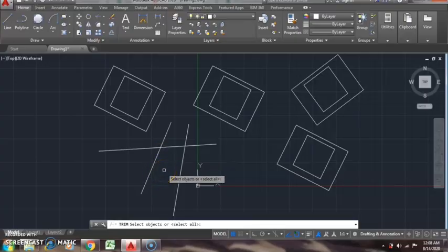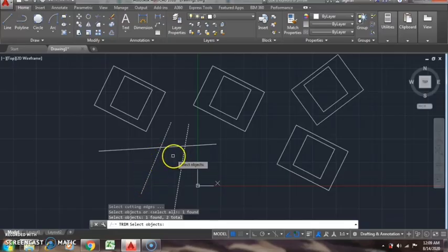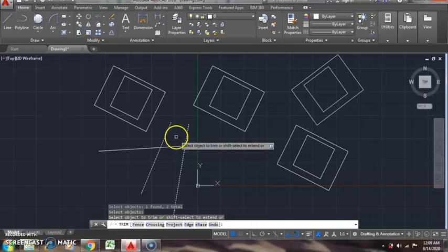For the first we can select the boundaries. Using this boundaries we can trim the object or trim a portion of object. For that, first I select the boundaries. Then I have to assign these boundaries. Just enter. Click on the enter button. Then trim. Trim about these boundaries.